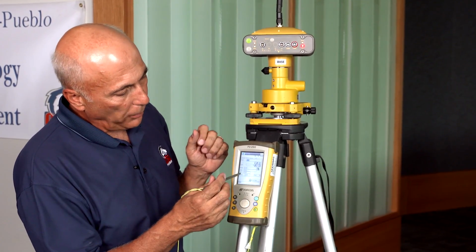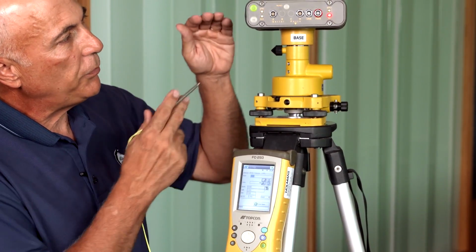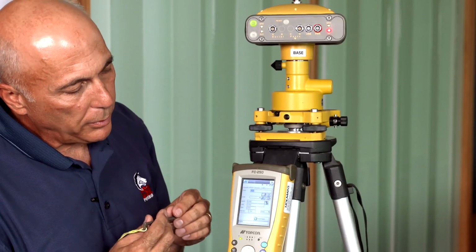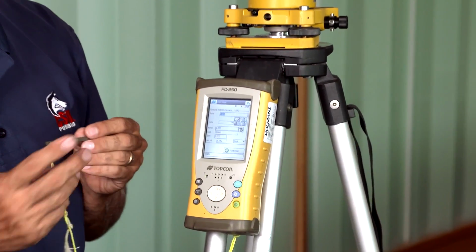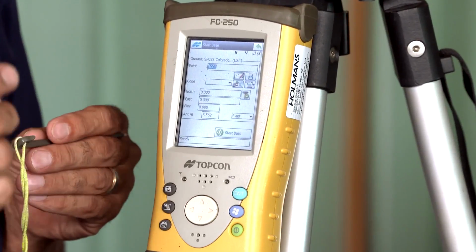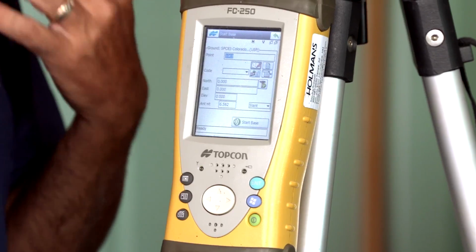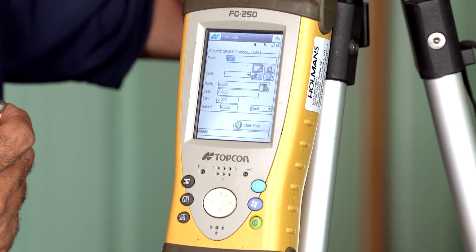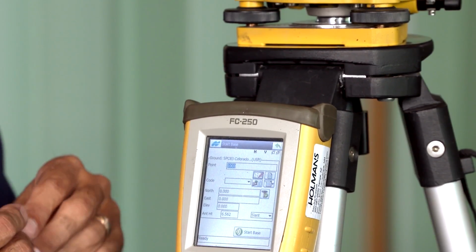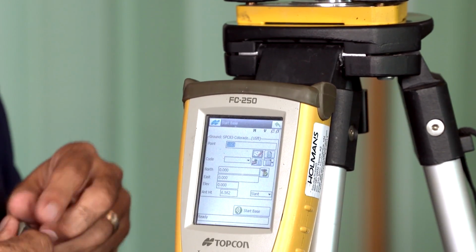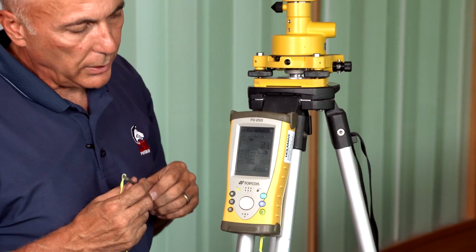Once we've set up our base unit, either by having it find itself or setting it up there, and once we've put in the height, then what we would do is tell the base unit to go ahead and start. And by most units, we'll have some sort of system to start the base. Once we start, the base will go into the communication port, which means it will then start sending the location of its signal, the signal location of its point right here, out to all other roving units within the area.